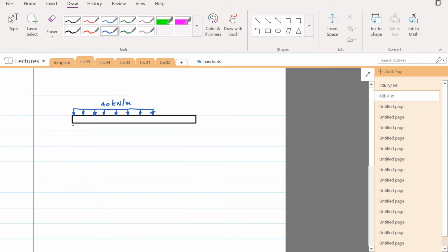Okay, so on the left side we had a hinge joint. So let's put two reaction forces there, one in the horizontal, one in the vertical direction. And then at 0.8 meters from the left, there was a roller, so I need to put a vertical reaction force. And on the right side, there is a force of 20 kilonewton. And then there is a bending moment of 150 kilonewton meters on the right.